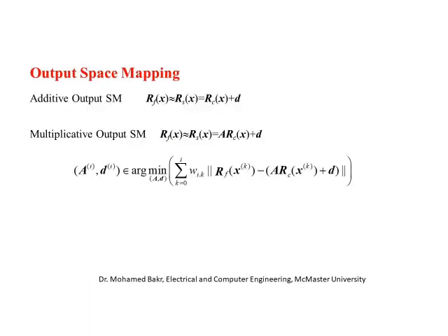Another type of space mapping, again, space mapping as a surrogate model, is called the output space mapping. In output space mapping, they say, okay, the coarse model and the fine model do not give us the same response. So why don't we try to correct the response directly? Don't change the parameters, but add a vector D to your responses. This vector RC could be, for example, the S parameters at different frequencies, or it could be the electric torque at different electric angles.